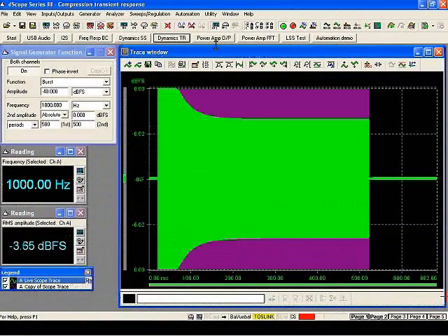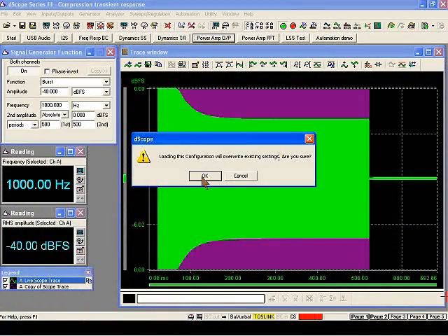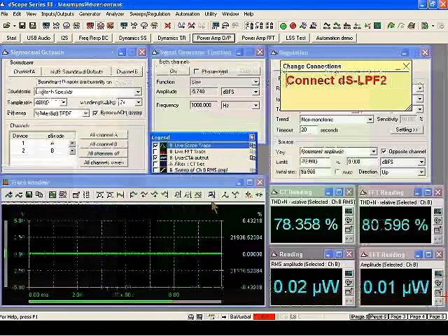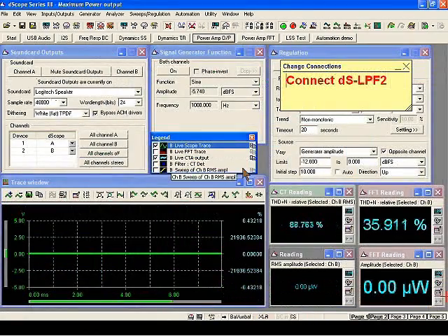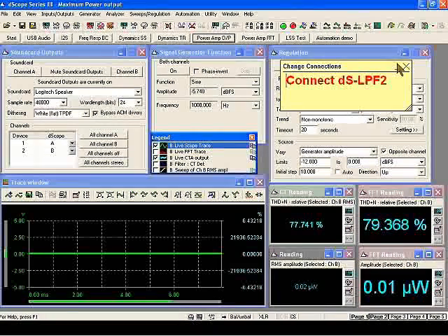So I'm going to load my first configuration file that relates to the power amplifier testing, and as I said, this first test is going to be related to analysing the maximum output power of my amplifiers. Again, I've just written a little note to myself in my configuration file here to connect my low pass filter, which I have duly done, and I can then minimise that memo.